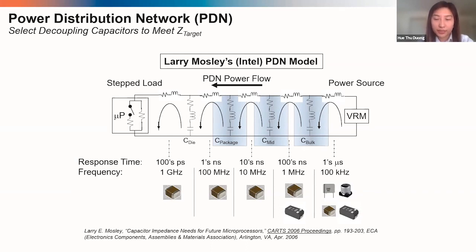At the lower frequency range, these demand higher cap values, which can be tantalum polymers, aluminum polymers, and even ceramics and film capacitors. And as you move closer to the load and the frequency increases, you need better frequency response, lower ESR, ESL, lower capacitance values as the frequency increases, which generally tend to be ceramic capacitors.